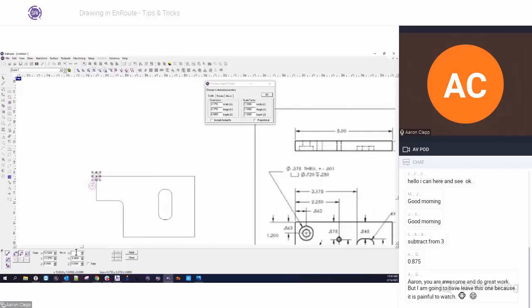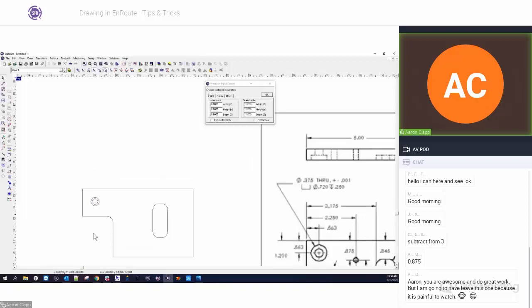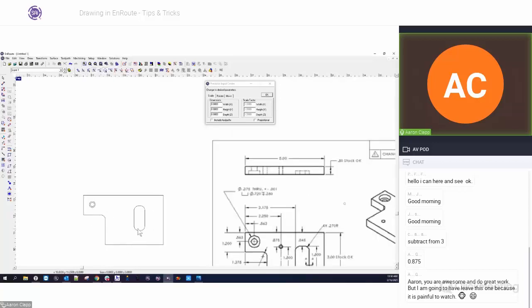So I'm going to say positive 0.563 and then negative 0.563 on the Y, because we're actually subtracting it from that. Hit apply, and now that's exactly in here, right where we want it to be. Now, obviously, our proportions I don't think are quite right. Let's see here.